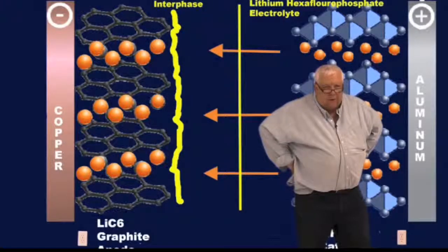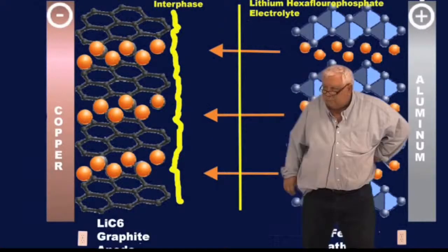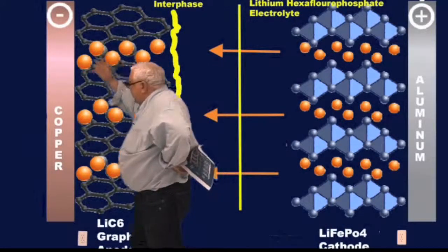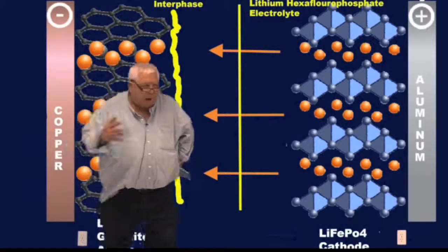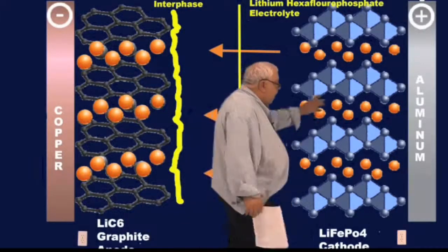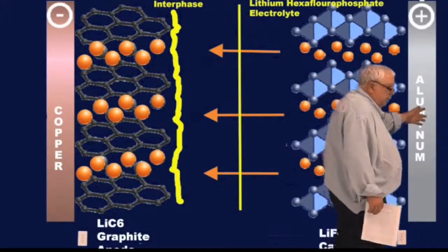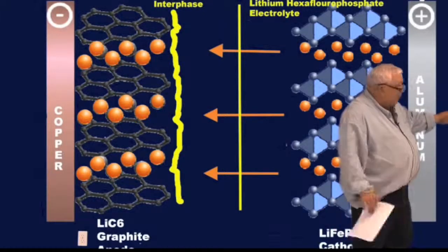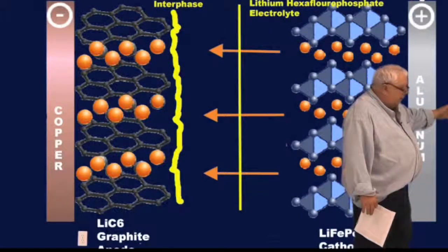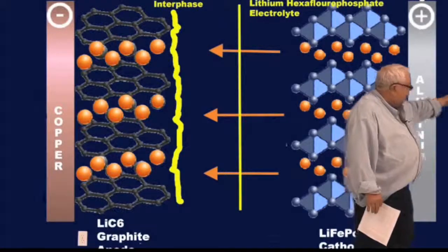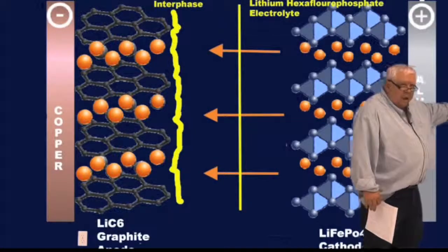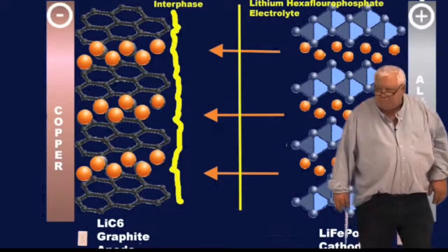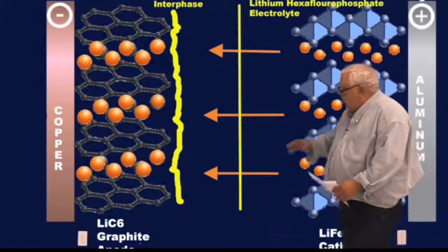And all is right with the world until we have depleted the number of lithium ions in the anode, and they have migrated to the cathode and intercalated there. Now, the next time we do this after the formative charge, there may have been 2 or 3 of these to make this happen, we can more easily extract electrons from the cathode side and pump them around onto the negative side.